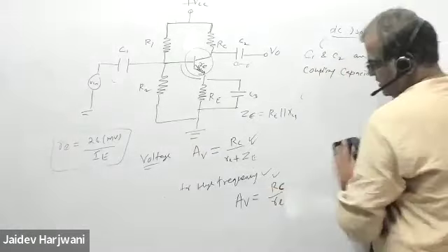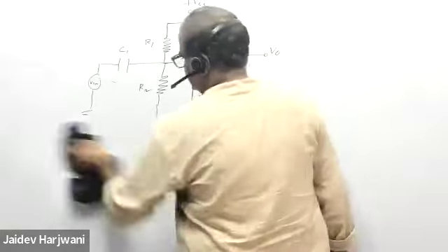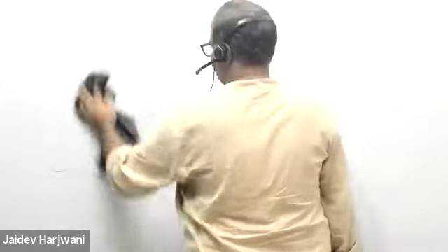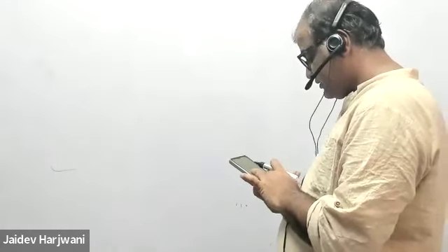So let us solve one or two problems on the gain. I'll give the solutions also, don't worry. Let us discuss first here. I have to draw a circuit again. Question number 1 says: for the circuit shown in the figure, find the DC bias level, the DC voltage across the capacitor, the AC emitter resistance, the voltage gain, and the state of the transistor.